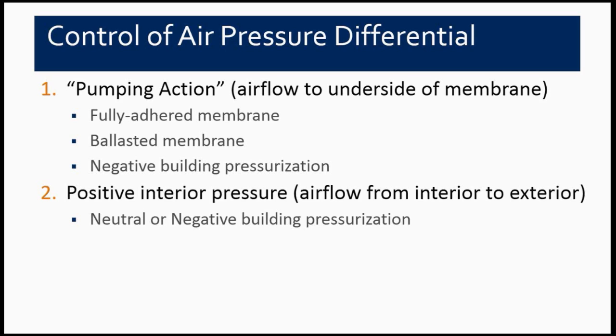And I keep saying that we did look into changing the system out to indirect fire. The cost of that in just maintenance and heating alone was huge because direct fired units are roughly twice as efficient as indirect fired units. And so there would have been huge long-term costs associated with that.